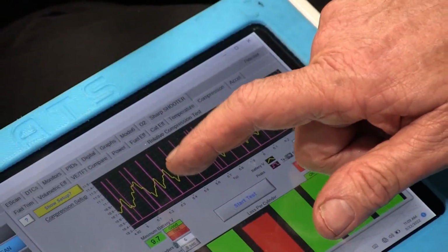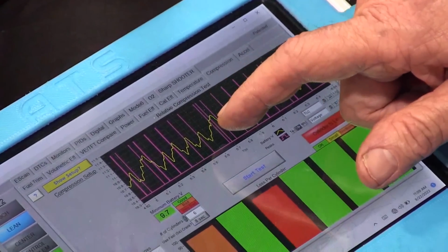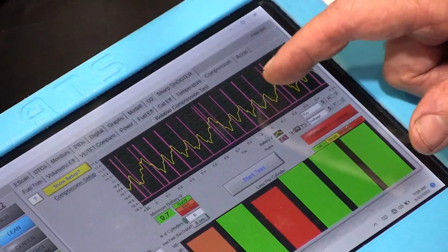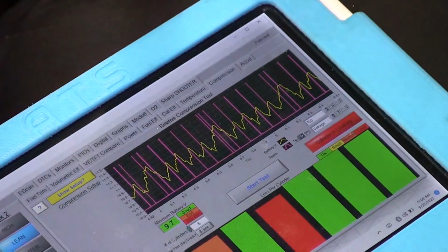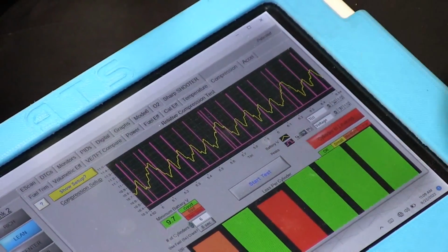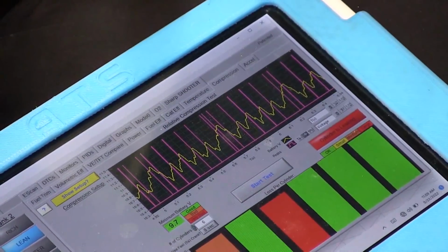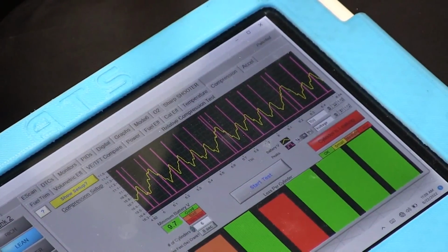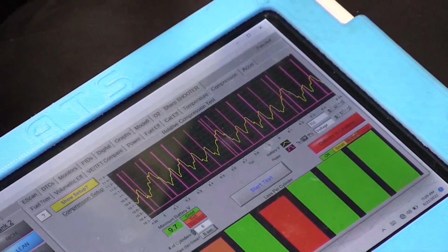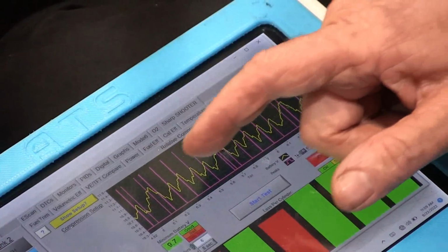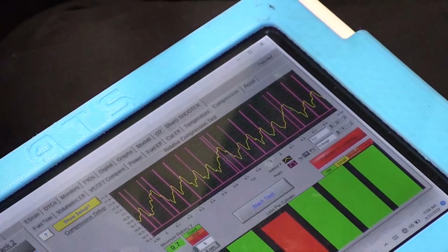You can see how we have current draw, and you see how we missed one right here? Well, when we missed one right there, that's a really low hole, guys. So this has a problem with the cylinder pressure. This is a cylinder pressure problem. And you're never going to fix that with spark plugs and injectors and all the other things they've done on this vehicle. This looks like we have an actual mechanical failure on this engine.